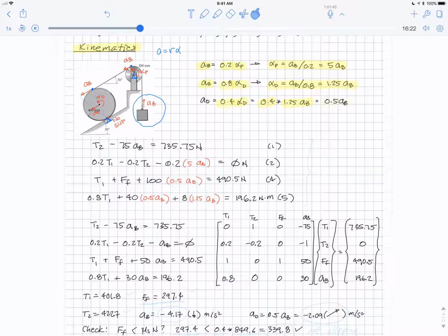Put that in there, multiply it all out, and you get half of a block. Now, this makes sense, right? If your acceleration is proportional to your distance from the pin, which is at the bottom, the middle of the disc is half the distance away as the top of the disc, so that's half the acceleration.